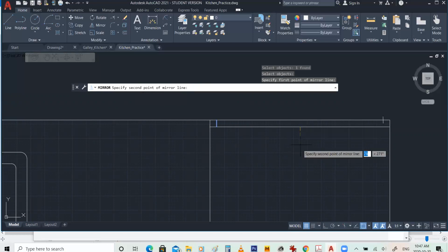So I'm just going to click and drag down. Now, as you can see, once I click and drag, I have a reflection copy of the segment that has started to be placed. Now I need to make sure that this line is going to extend at exactly a 90-degree angle, perpendicular. So if ortho is not turned on, I need to make sure that ortho is turned on now. And once I click on it, you can see that I have placed the line. Now the line is placed. Now to complete the operation of the mirror command, once I extend, I need to click.